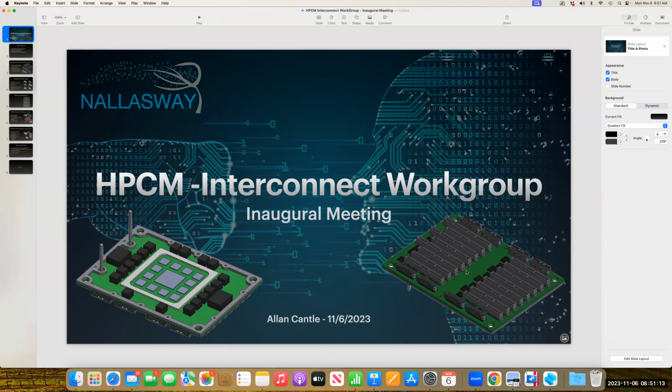I think the same kind of thing applies. We look at your application, and maybe changing from the through hole board lock to SMT is also application specific. In the SFF standard, they specify up to 200 durability cycles. Basically, the connector needs to hold up to 200 mating cycles.